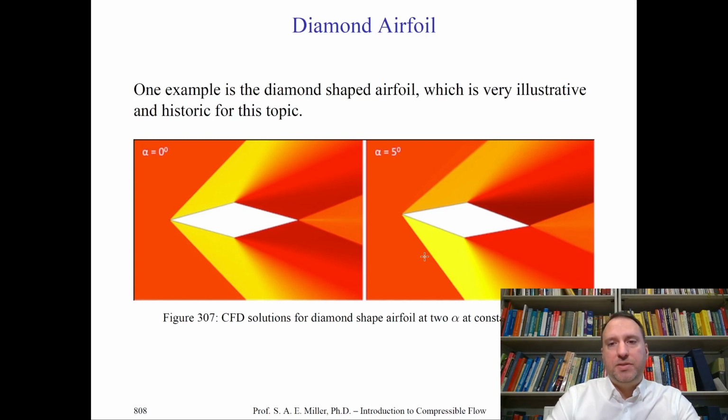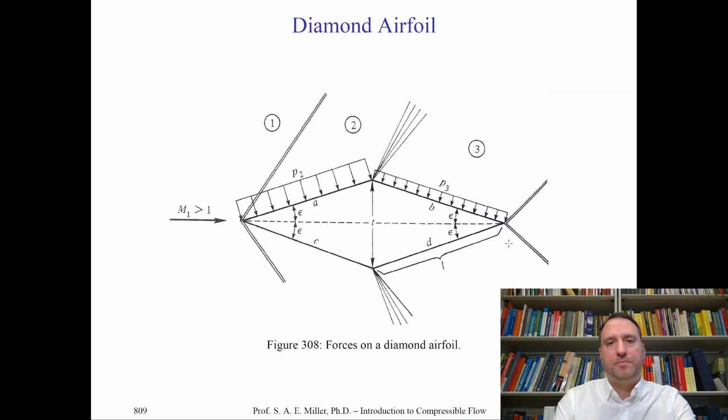It's very much true also that you can see the flow is everywhere supersonic in these cases. For example, we do not have detached shocks, so there's no reason to expect we have subsonic flow in these particular flows, unless, of course, the Mach number is in the transonic regime. Let's try and analyze these particular cases with our newfound tools and also make some notes about them in the following slide. Let's do that now.